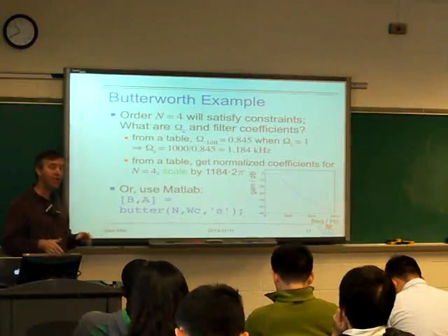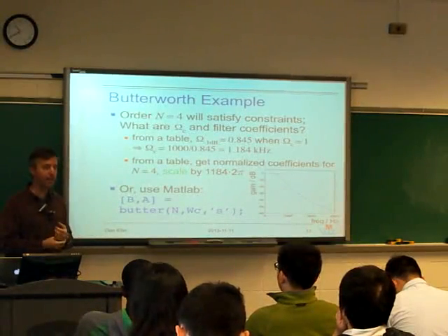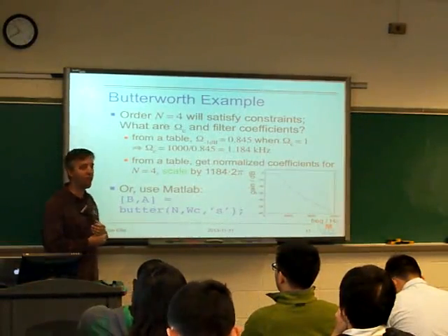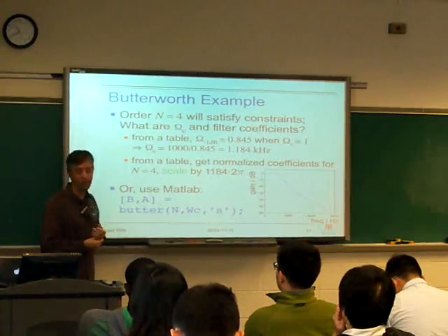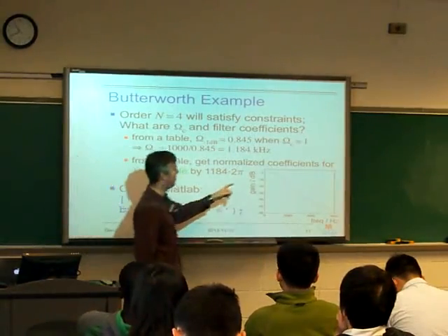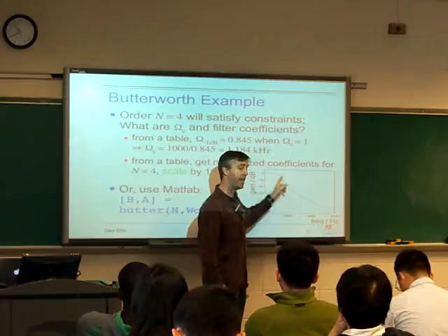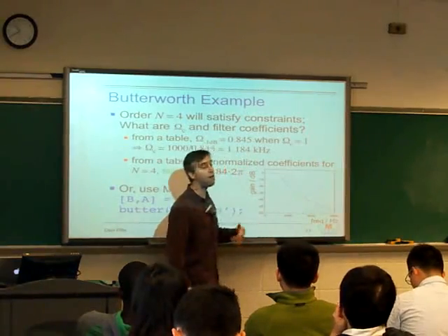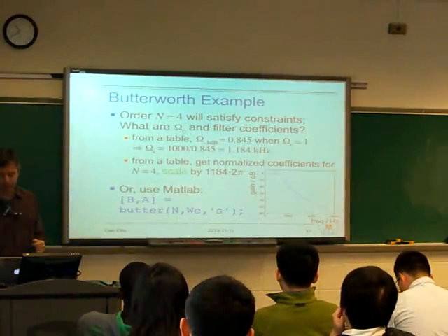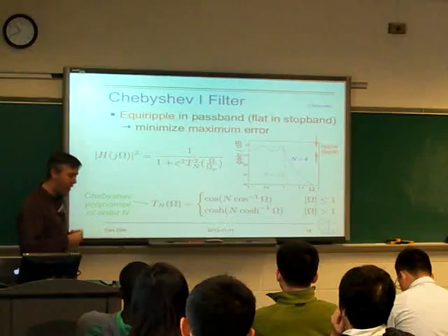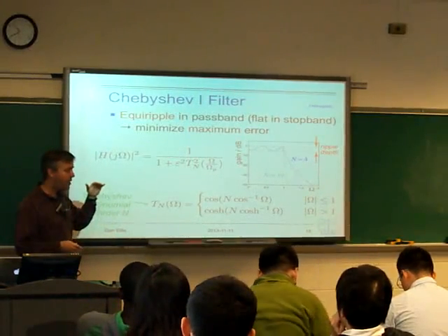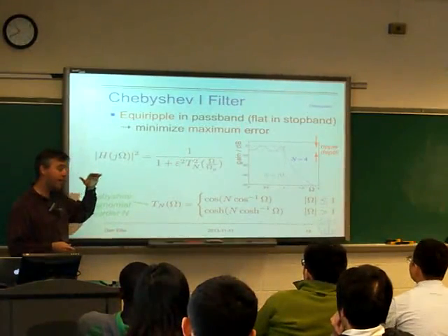So that was our first analog filter, the Butterworth filter, which is hugely important and very widely used, but also pretty simple and not particularly dramatic in its performance. It has a fairly slow roll-off because you've got this nice property of monotonicity of the gain. The second class of filter was, okay, now we're going to start introducing ripples.